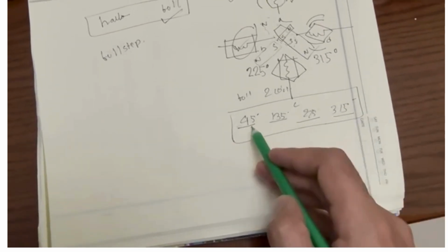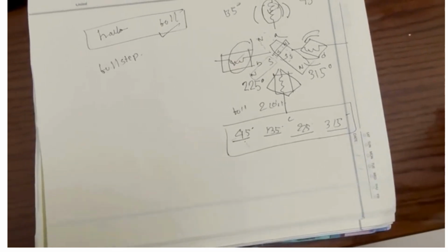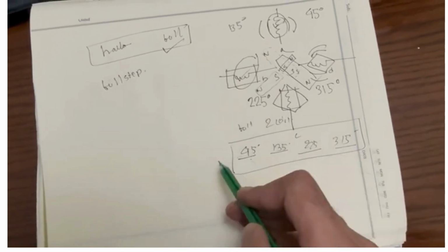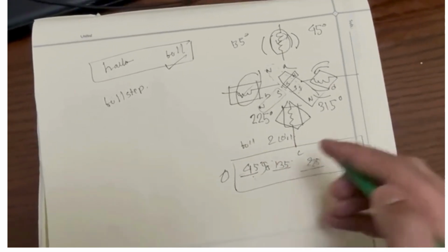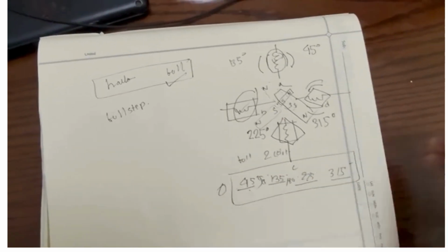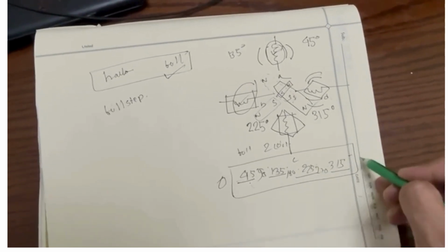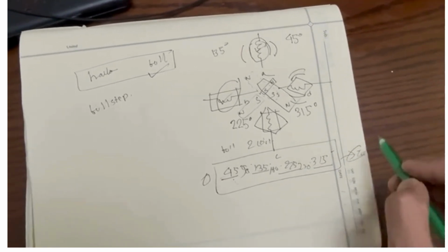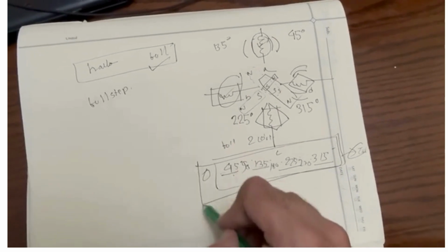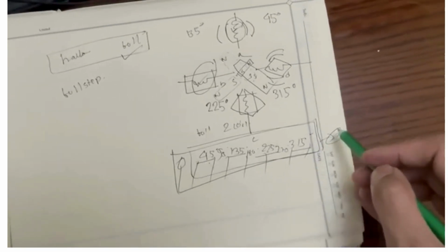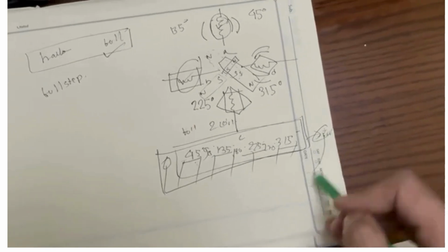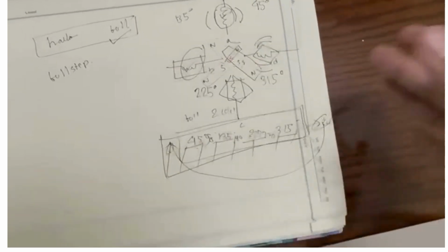There are a total of 8 steps instead of 4 steps in half step mode. Here are 0 degrees, 90 degrees, 180 degrees, 270 degrees. And last of all, it goes to 360 degrees, which is not counted. We count up to 315 degrees. Here a total of 8 steps are there, because when we go again to 360 degrees, we are basically coming back to 0 degrees. So for this reason, I am not counting that.